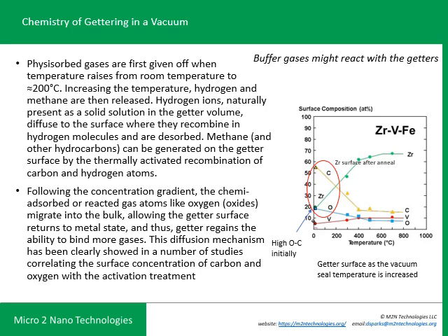So will the buffer gas react with the getter? You've got to think about that as well. Ideally, you choose a buffer gas that would be a noble gas like argon, neon, or helium. They won't react with thin film metal getters.